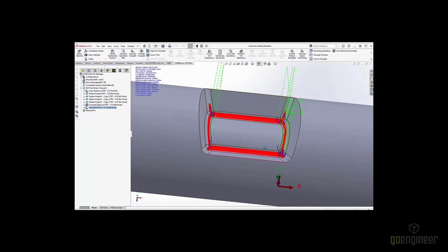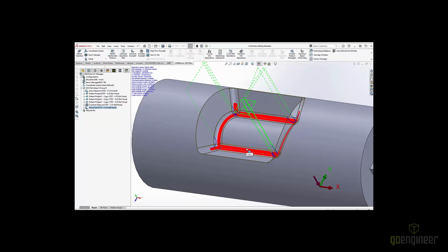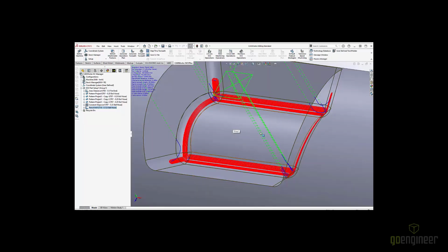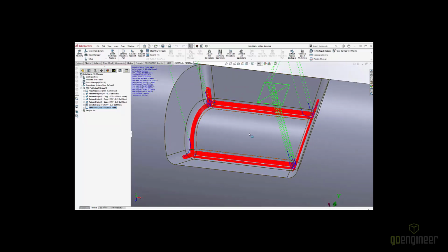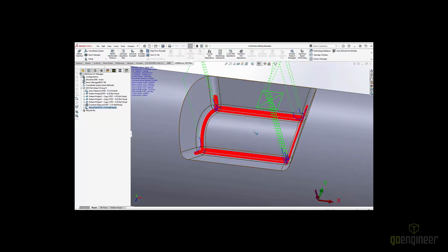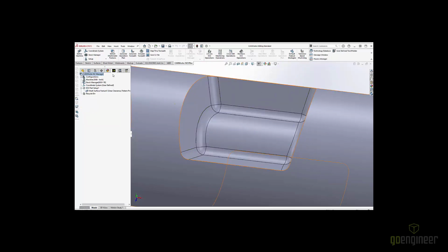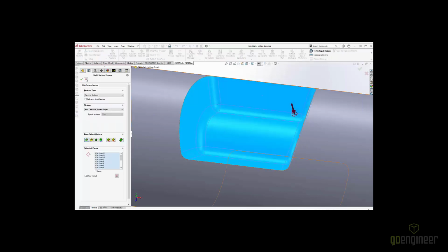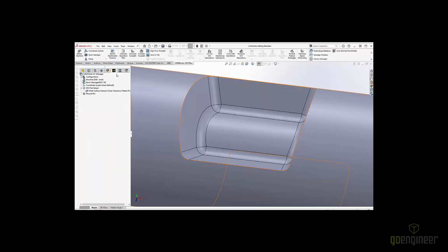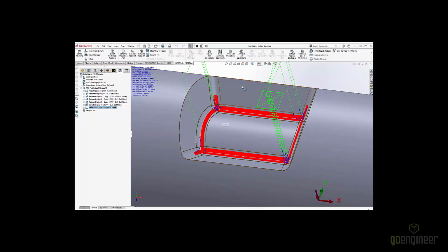There's also pencil mill, another really good one for getting good surface finish, good final parts. Its whole job is to just tuck into the corners, the sharpest places, the tightest places, and focus on those areas only. All of these toolpaths are created off of that same set of features, which I can highlight real quick to make clear. All the generic 3-axis finishing toolpaths and roughing toolpaths pretty much go everywhere, but you can see that pencil mill doesn't care about all the flat, broad surfaces. It's just worried about sharper corners.